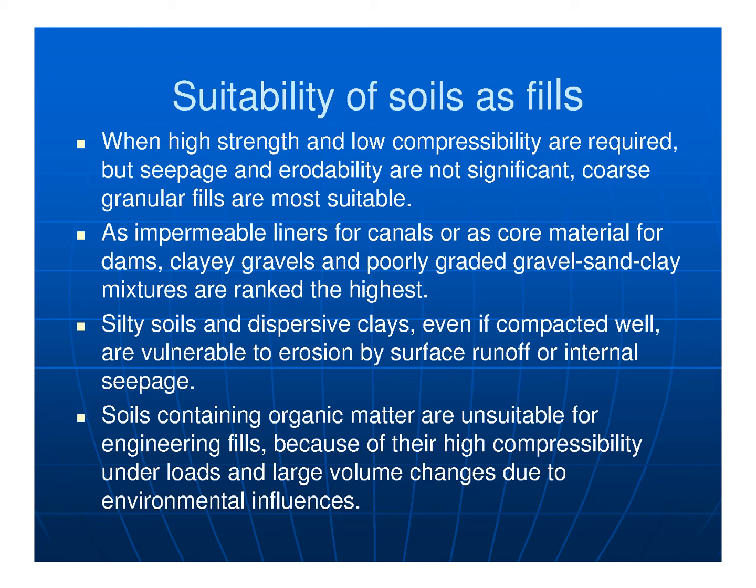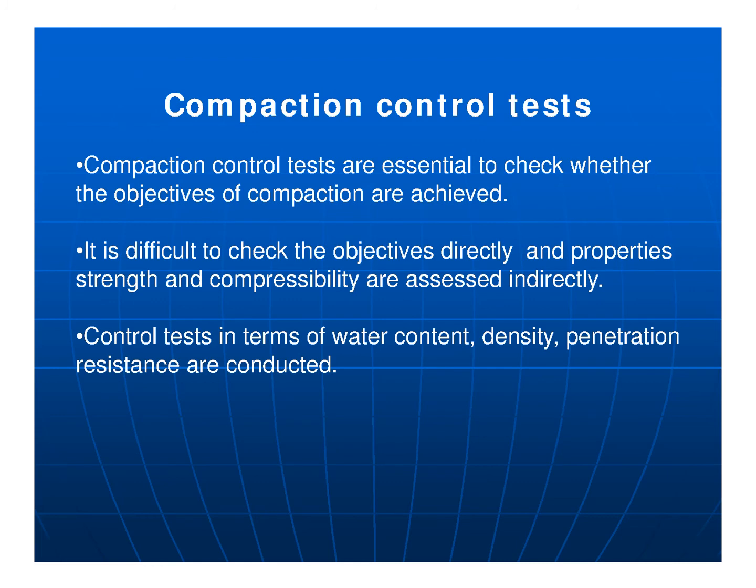Soils containing organic matter are unsuitable for engineering fills because of their high compressibility under loads and large volume changes due to environmental influences. Common control test. Compaction control tests are essential to check whether the objectives of compaction are achieved or not. It is difficult to check the objectives directly, and properties, strength and compressibility are assessed indirectly. Control tests in terms of water content, density, penetration, resistance are conducted.